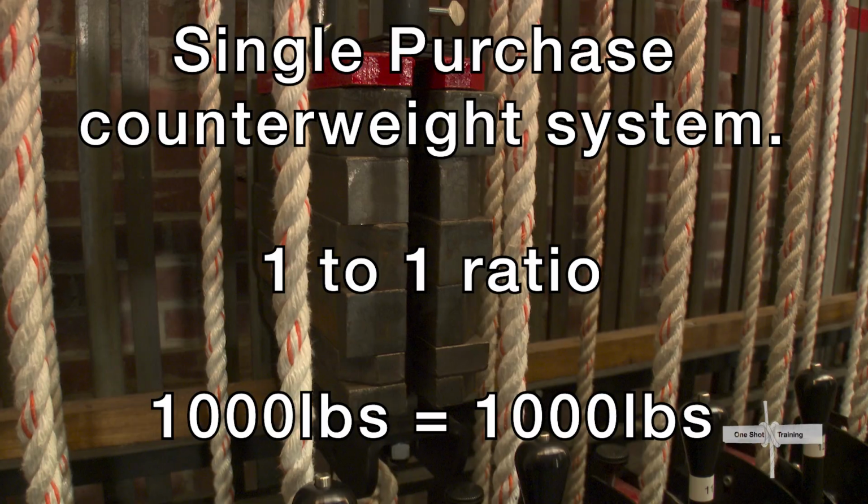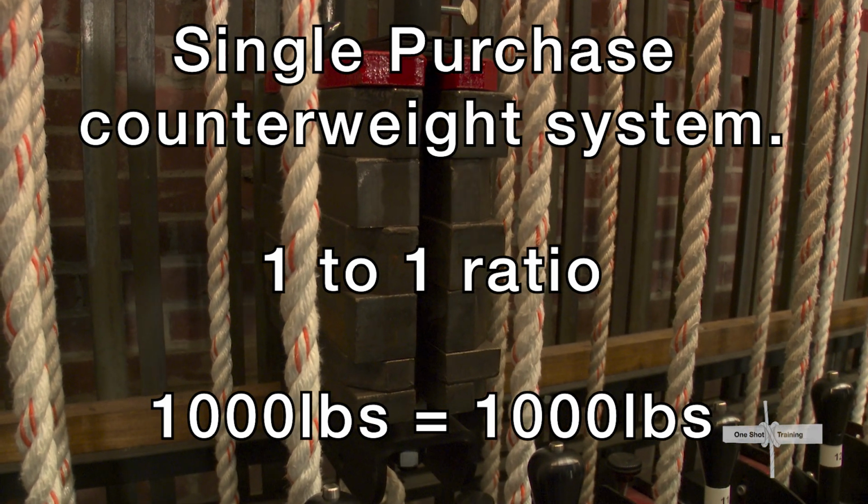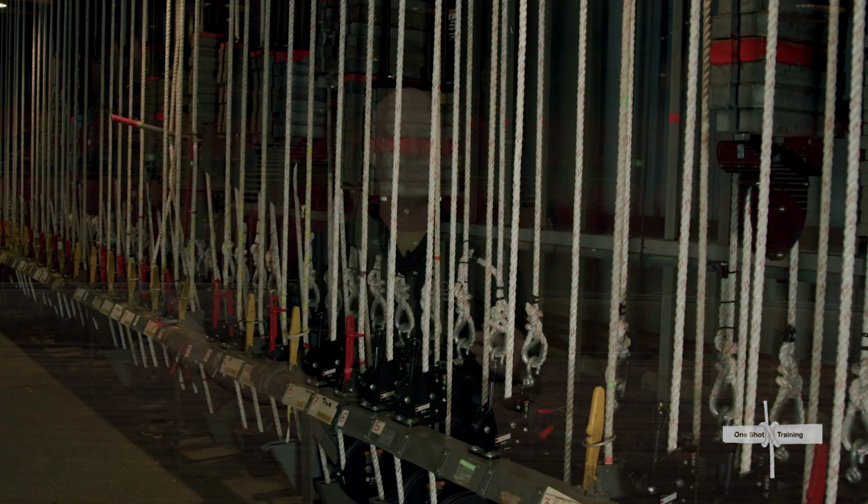In a single purchase system, you have a 1-to-1 ratio. In other words, if you put 1,000 pounds on a batten, then you need 1,000 pounds on the counterweight arbor to offset it. So let's say you need to move the batten over a greater distance, or you want to have more operating position and lock rail up off of the floor to give you more space on the floor, or what we call swing space.